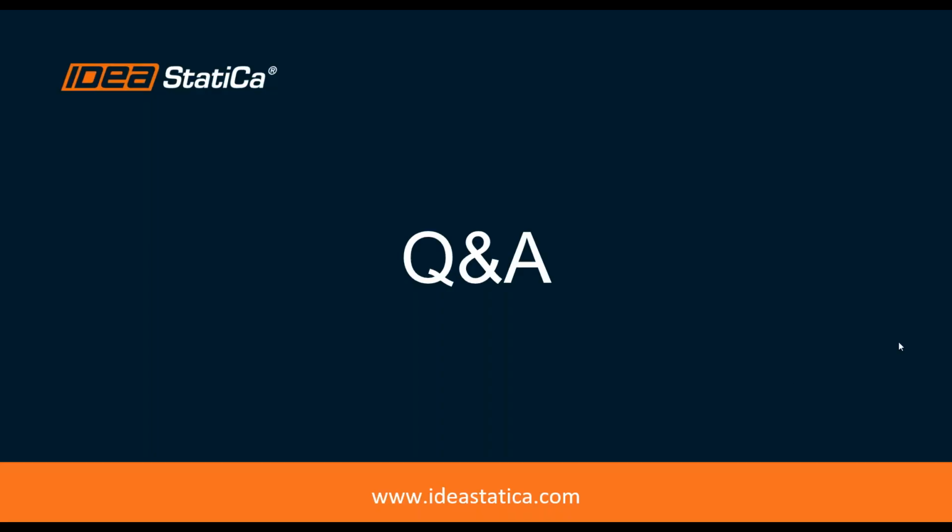Thank you. This is a very good question. So the tabulated data method in Eurocode has its limitations, and because this is right now the only method implemented in our concrete applications, we have to go according to these limitations. And in the method, there are only the rectangular, circular, T-shaped and I-shaped cross-sections described, so we cannot really go into more complicated shapes.